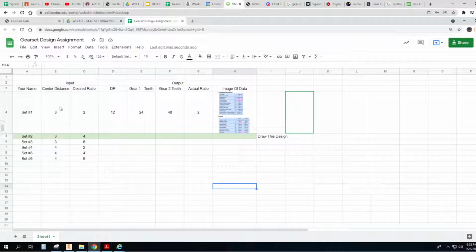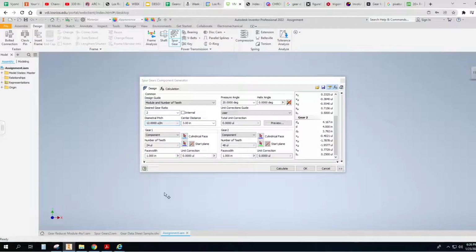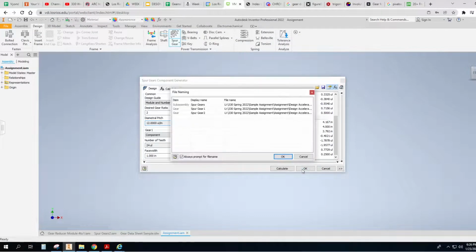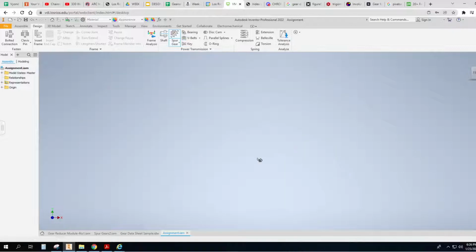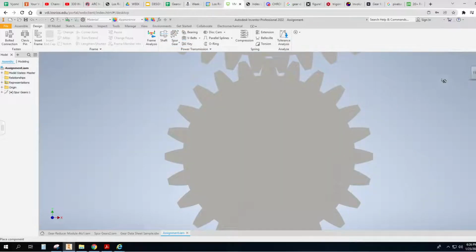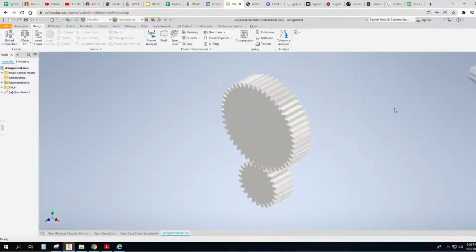So what you'll find is often you don't know exactly what you want, so you put a table together. Okay? So I want you to put this table together using Inventor. And voila. It says, do you want to really make that thing? Yeah, I want to make all that. And there it is. Click. And there they are. You could even take a picture of those if you would like and put that in there too.